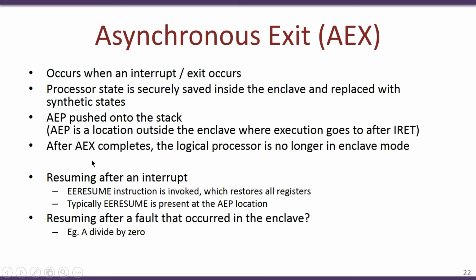So, this deviates from how interrupts are typically managed. As we know from earlier classes, whenever an interrupt completes its execution, this is done by the IRET instruction, and the IRET instruction would essentially restore the previous context, and the program which was executing prior to the interrupt occurring would continue to execute.